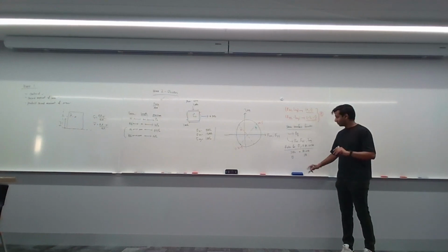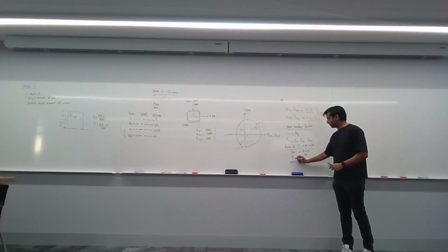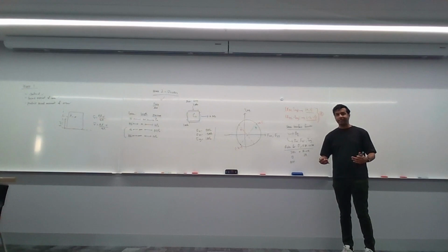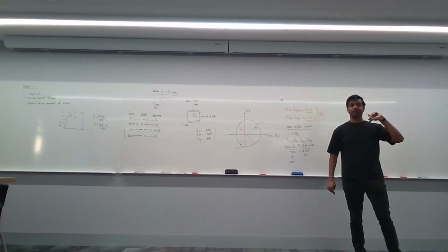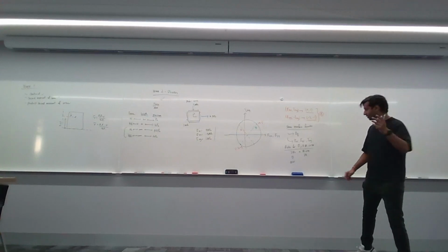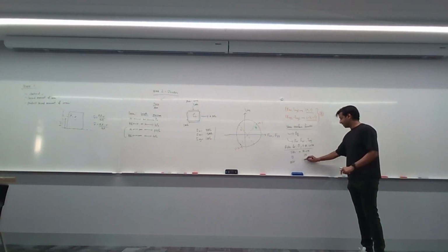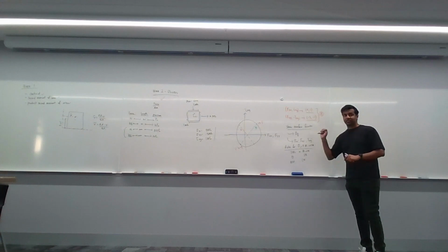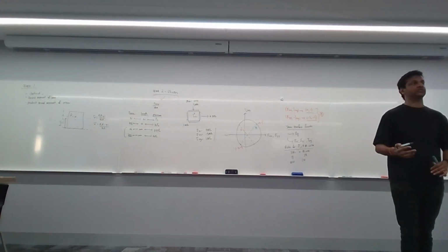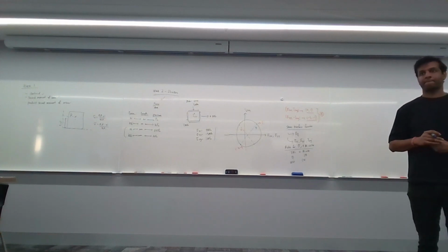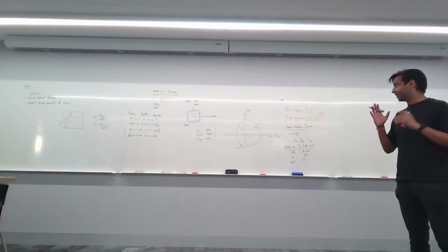Now, if you rotate by, say for example, an anti-clockwise direction in real life, in the Mohr circle, you will rotate in a clockwise direction. This is what you have to remember. Okay, which you pointed out correctly before. The direction is flipped for stress and strain Mohr circle, but importantly, the direction is not flipped for your I value Mohr circle. Okay. You got to keep that in mind.